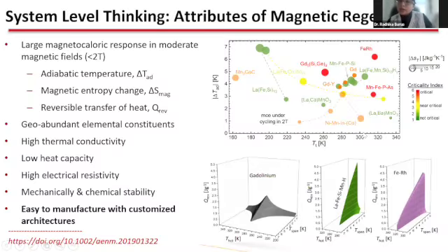And you can see over here that the best magnetocaloric material, at an applied field of 2 Tesla, is, of course, iron rhodium. I've done a lot of work in the past with iron rhodium. Excellent system when you look at it, but extremely expensive. Rhodium is a critical material. You don't want to make a regenerator with iron rhodium.